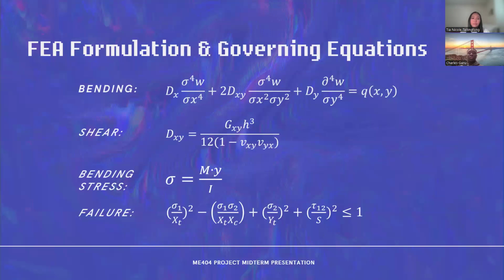And then going to the calculations that were done from these equations, we can say that our failure criterion value is 5 times 10 to the negative 6. So that's way far below 1, and the structure is very soundly safe. And if we also talk about our bending and shear calculations, the shear rigidity is 458 newtons per meter. And the maximum bending stress would be 10.88 kilopascals.